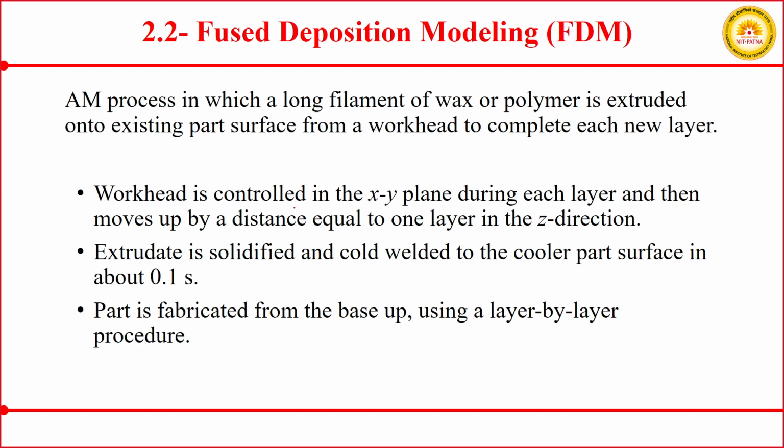The workhead is controlled in the XY plane during each layer and then moves up by a distance equal to one layer in the Z direction. Extrudate is solidified and cold welded to the cooler part surface in about 0.1 second or even less than that. Part is fabricated from the base up using a layer by layer process. So in the case of fused deposition modeling,